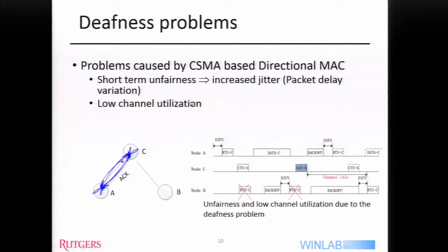A question again. When everything was idle and A transmitted the request to send, C has no way of knowing that the request to send is coming from that direction. So its beam can be pointing nowhere. You cannot assume you have both transmit and receive antenna gain.